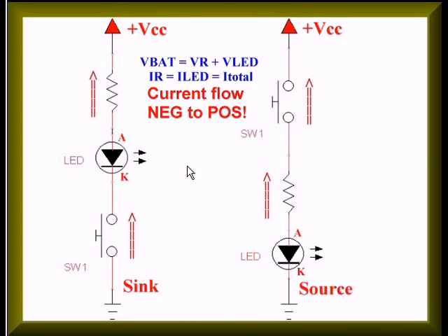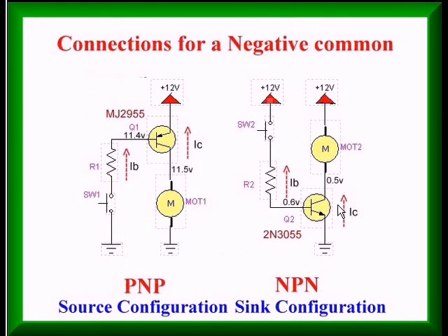This is important to note, these principles here, because that determines how your transistor switch will connect in the circuit. Again, note, if the switch is in the ground side, it's a sink. If it is in the high side or VCC, it is a source connection.